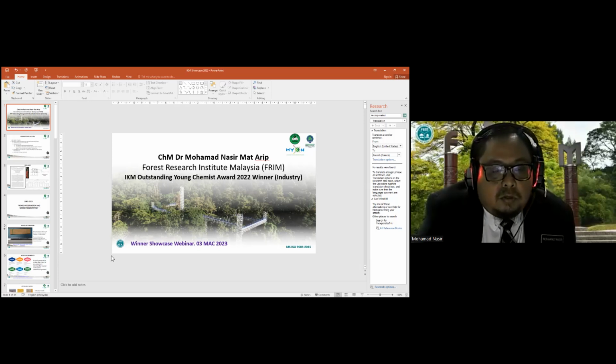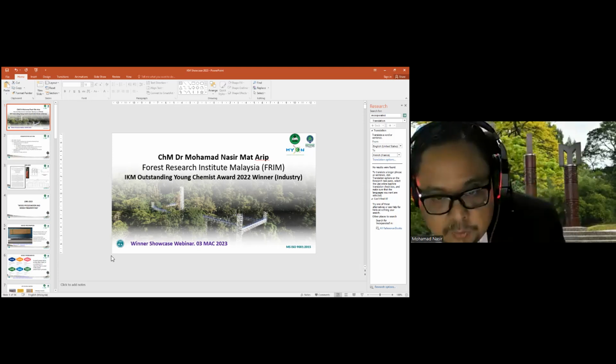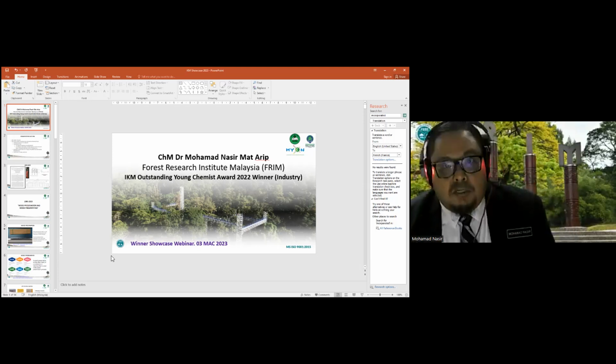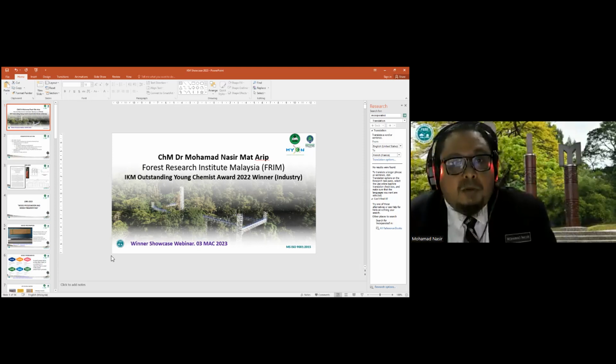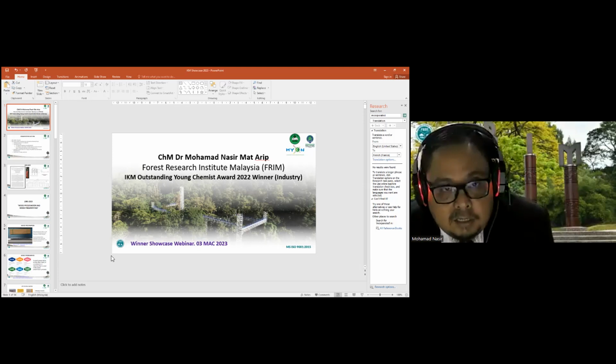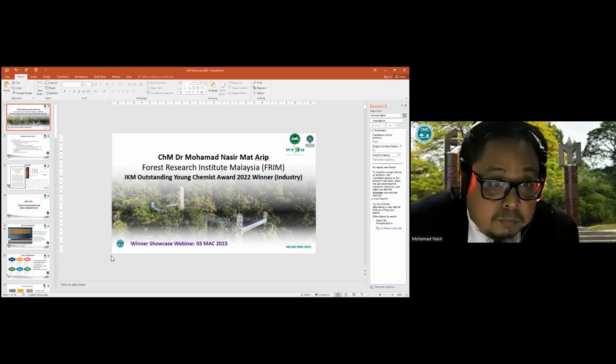And we also need to consider the species of the wood, and Malaysia has a grading system for durable, less durable and non-durable wood. So the most durable ones may not need to be treated, like cengal and the expensive wood, merbau.